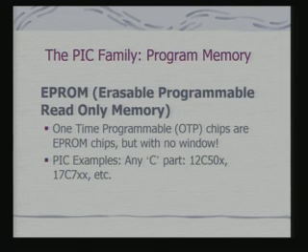So, when we are doing a mass production of an embedded system, the software development cost goes into NRE, that is non-recurring cost, and after that I simply write that program onto the EPROM and produce a chip, and that program is not expected to be changed ever after. And these are particularly intended for very low cost applications. So, when you buy a PIC processor, you should look for C. If there is C in its number, that means it has got an EPROM as a program memory.